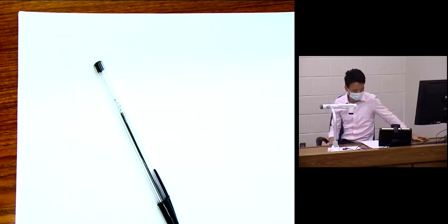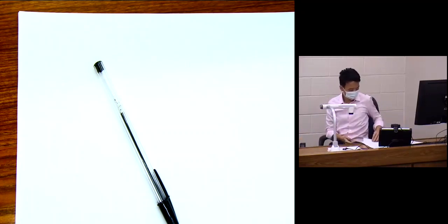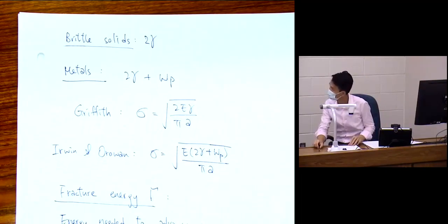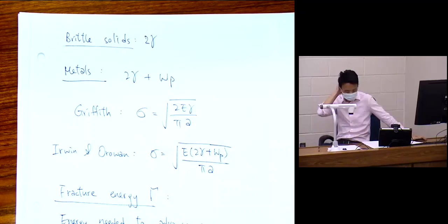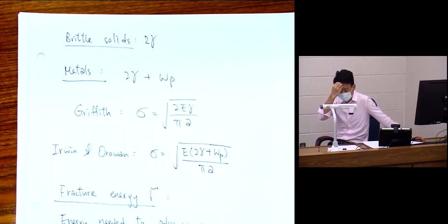He had the notion of surface energy, and he completed a thermodynamic energy analysis, and from there we derived, from the work of Griffith, an expression for the critical stress. So this is where we got to last lecture, right? And so we finished the analysis performed by Griffith, and it has a lot closer agreement with theoretical strength. And we remember he did two experiments which were very insightful, right?